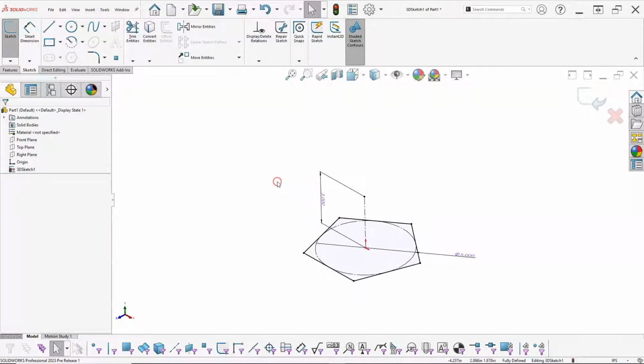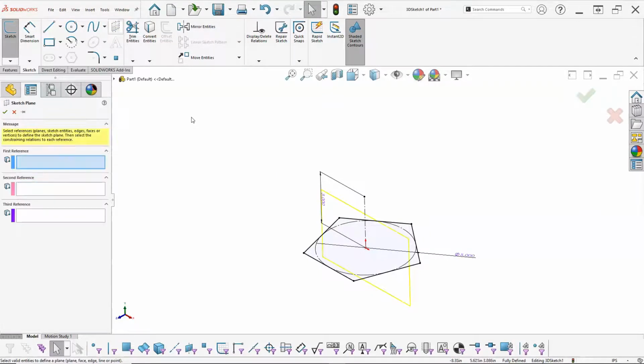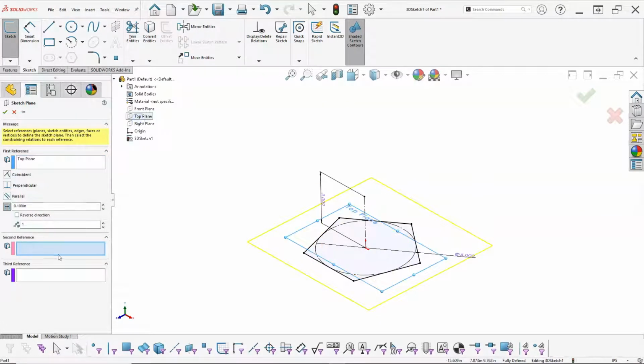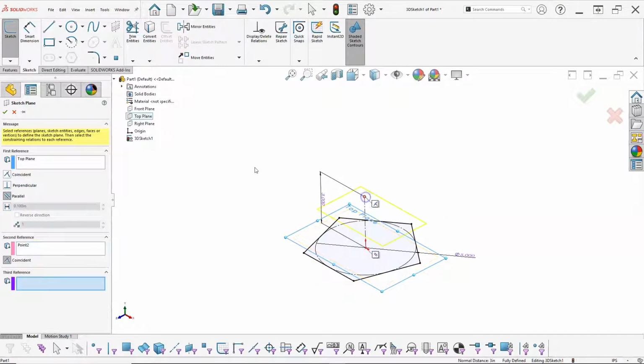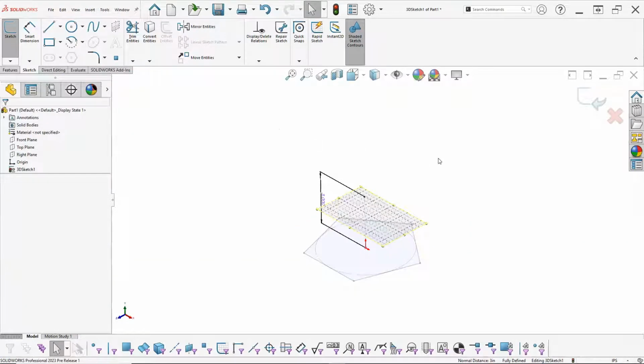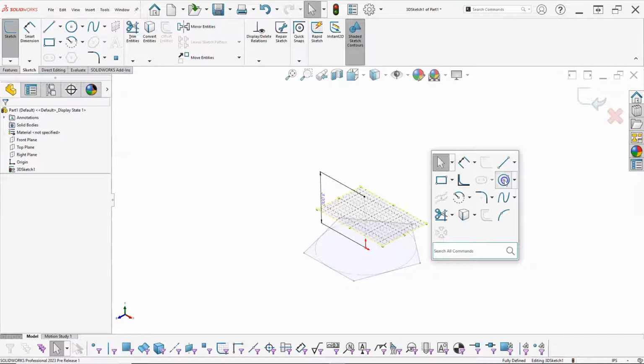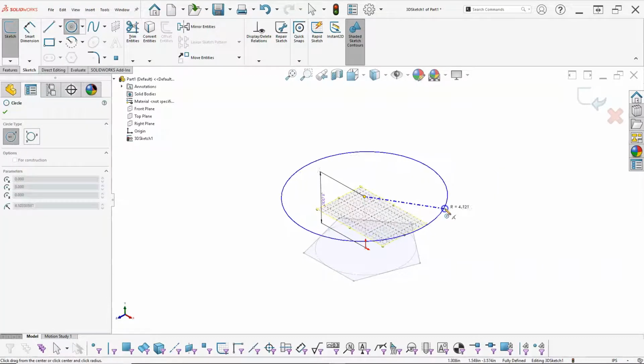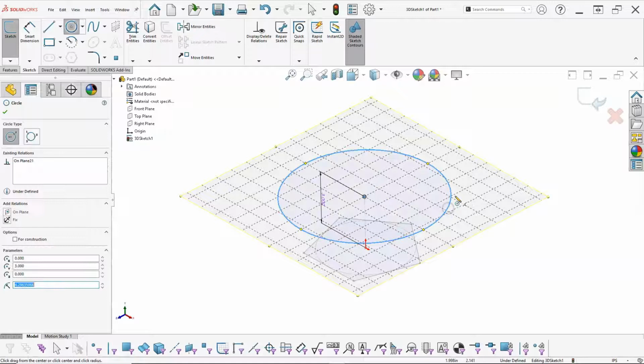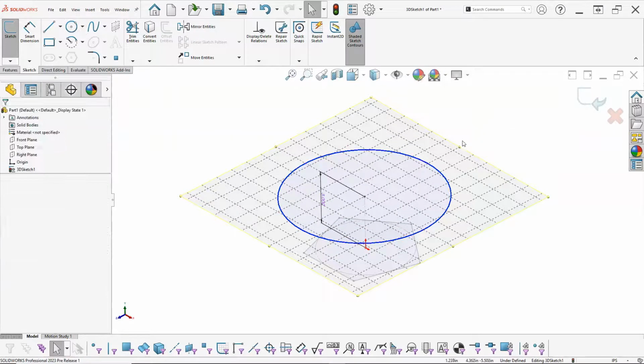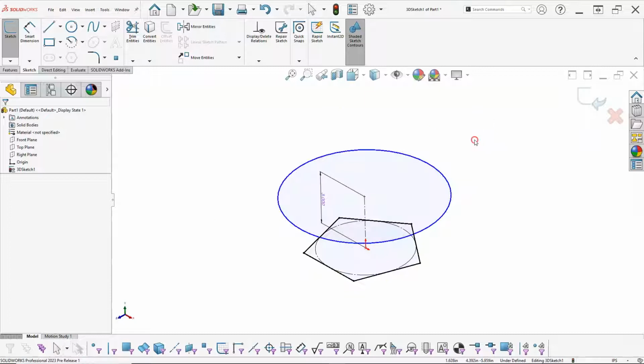And when we use the sketch plane, it's inserting a plane into a 3D sketch. We'll go to the top, and then it's going to be parallel. Since I didn't pre-select my items, they're not jumping right in. Alright, so we can go to our circle. I double-clicked on that plane, and that plane becomes active. And it shouldn't matter if this is a construction circle or an object circle, so we'll stay with it.